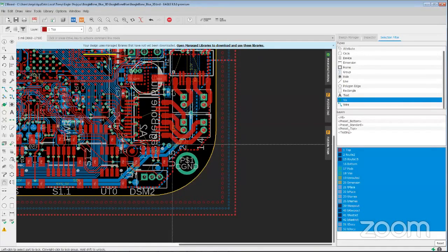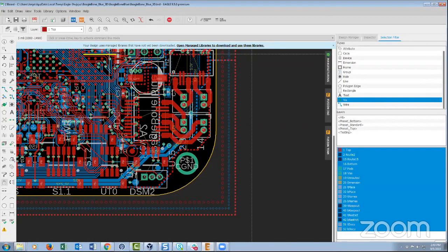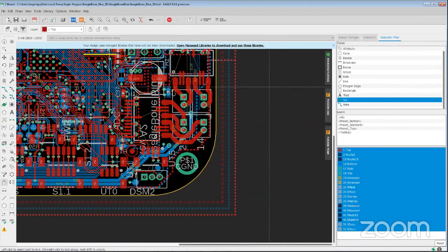And also on the filters that you were mentioning earlier, Jorge, a nice thing is that you could use it to pin down a particular footprint that is being used. That way you could switch them to another one if you wanted to. For example, you could create a filter of all the 0603 resistors of 100K.